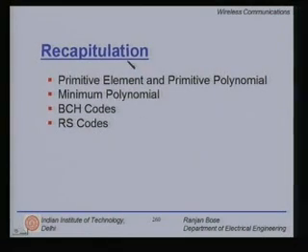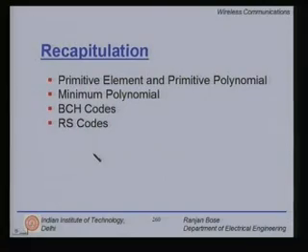The whole philosophy of coding is to add redundancies in a known manner, which is done using linear block codes. However, we can add another dimension to it, which is the memory part. That means the same input bit stream may not be encoded as the same output bit stream if you are ensuring that a system with memory is used.